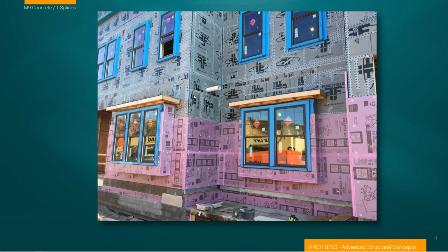We have a barrier layer and a barrier layer on top of it. And then the possibility, which is what we've really learned in rain screen systems, that all systems have points of failure where moisture can get in. And because these two are touching each other, there's a great ability for capillary action to take over. And I'm sure the argument by the designers of the facade was that no moisture will get back there because this is sealed. And if it does, it can't get through the building because this is sealed. And I think that's the primary way that we see these failures in rain screen systems, or failures in wall systems, and why this constant reminder about the value of rain screen concepts in construction is so important.